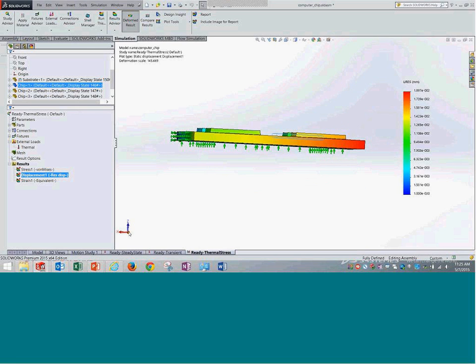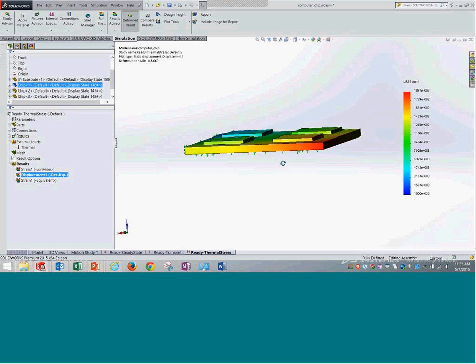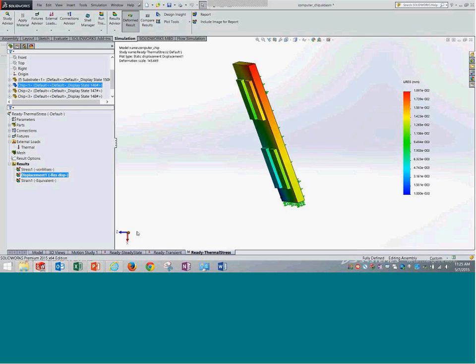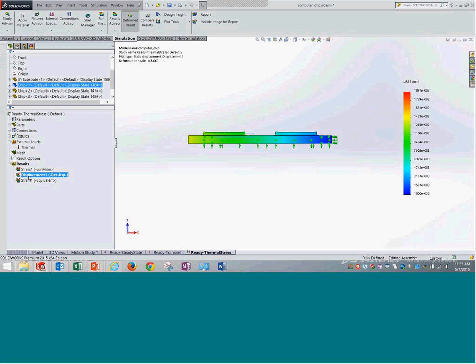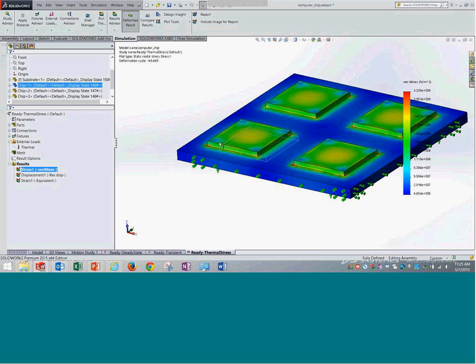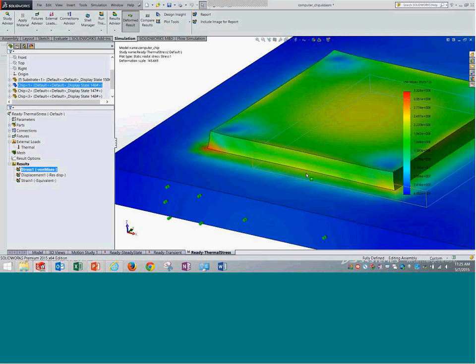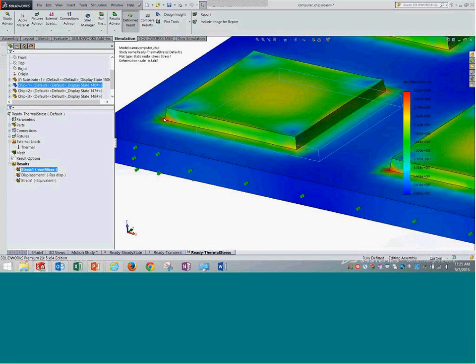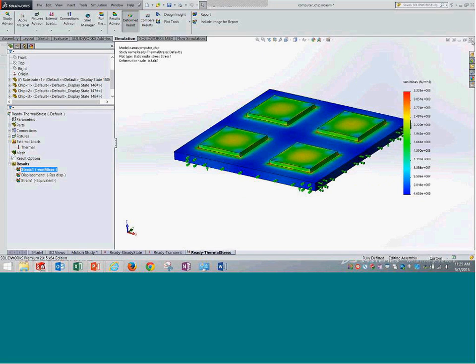So in a way, this part is trying to expand in the center. Actually, it has no space, and it may even be moving in a direction perpendicular to that, and it could be going up. That's what explains the creation of stresses. If the chips are connected to the porcelain material, the coefficient of expansion could be quite different, and that can create a comparatively larger amount of stresses and strains along that particular axis. Not many more things to be interpreted in this analysis, but this is what I'd like to highlight.